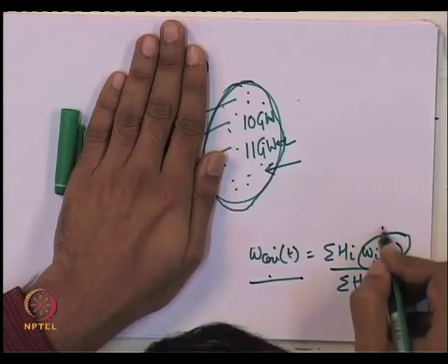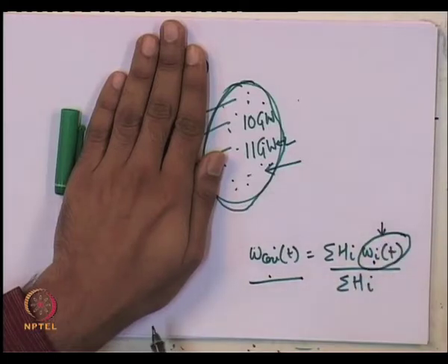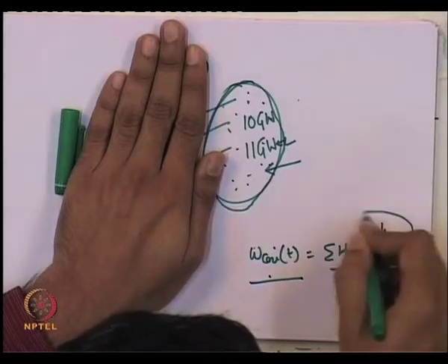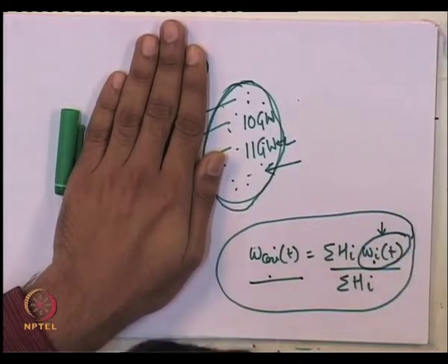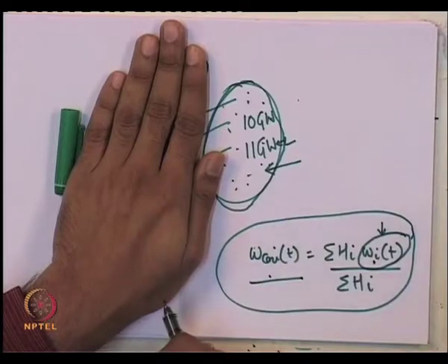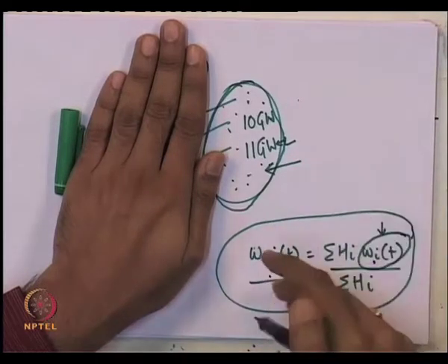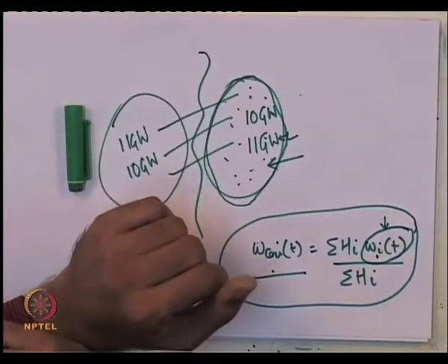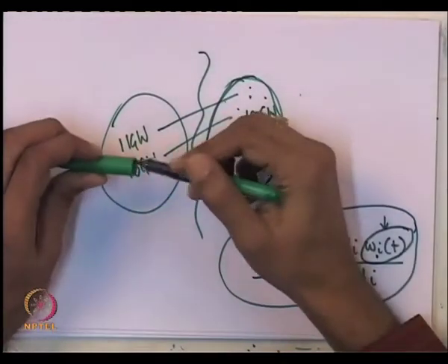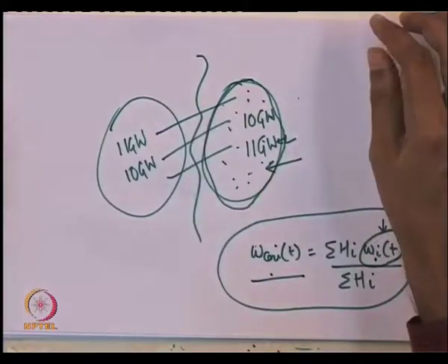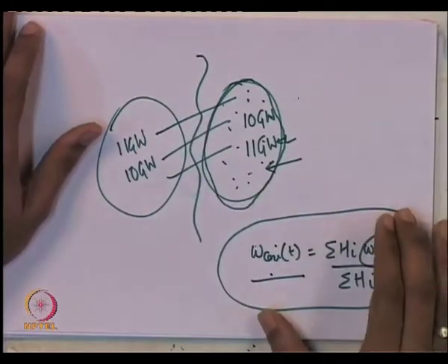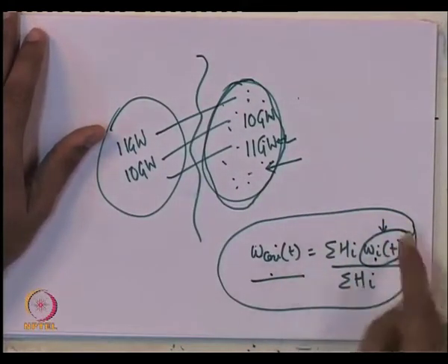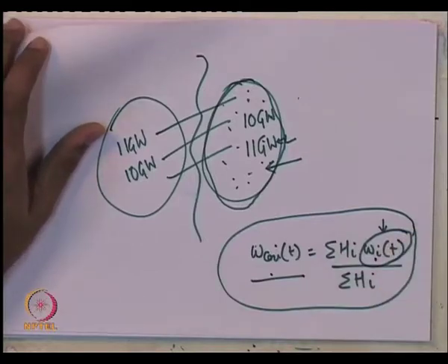So, you need to time tag all the frequency measurements, send them to a common location and compute this for every time instant, and then take the derivative and then do df/dt relaying. So, this is one particular scheme, where you can use proper technology and actually compute this and derive a good scheme for under frequency relaying.